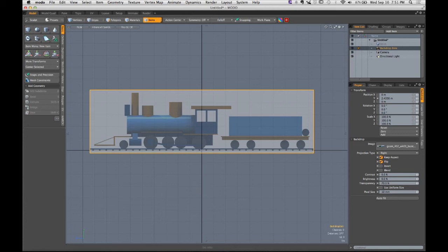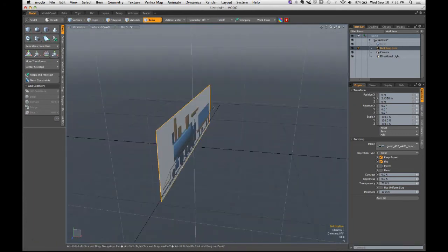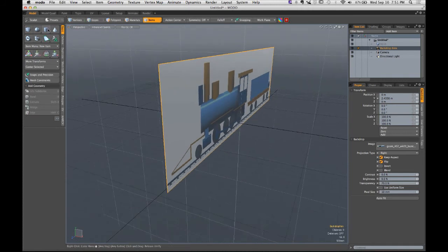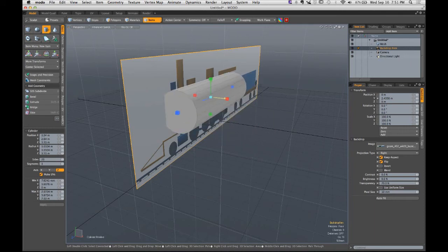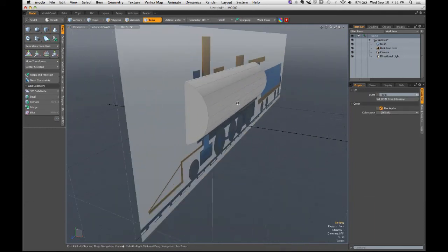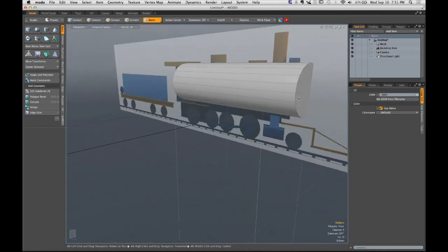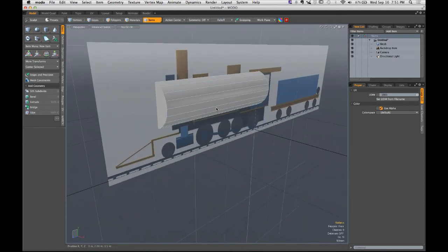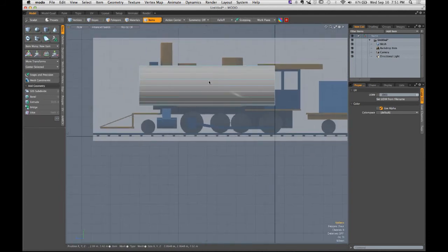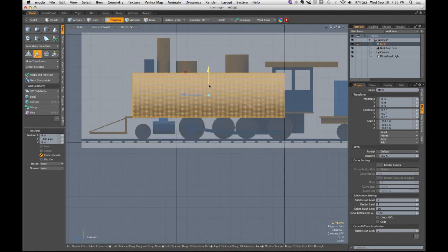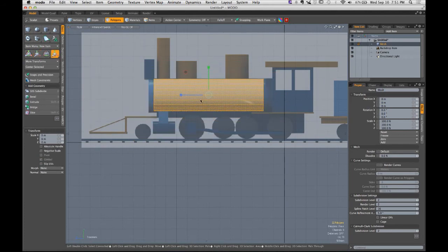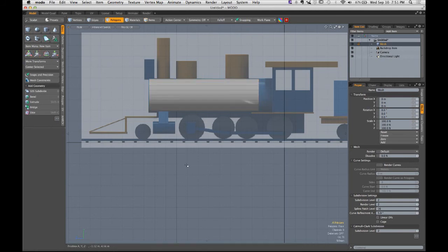One final thing about backdrop items, then we'll move on to some really cool things. Now, when we're modeling here, we're often going to be having geometry at the exact same location inside of our scene as our backdrop item. It would be great if I could see through my backdrop item in the perspective viewport, and same when I'm looking at my scene from the right. I would love nothing more than to see through to the image in the back, because how can I understand the size of this thing when my polygons are getting in the way? Here's how we fix it.